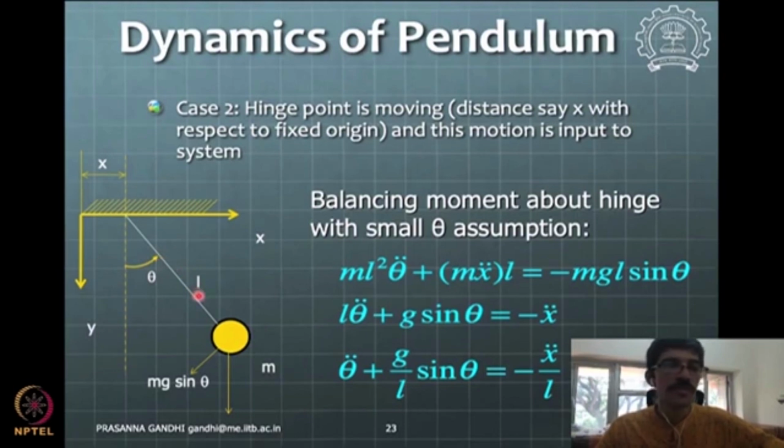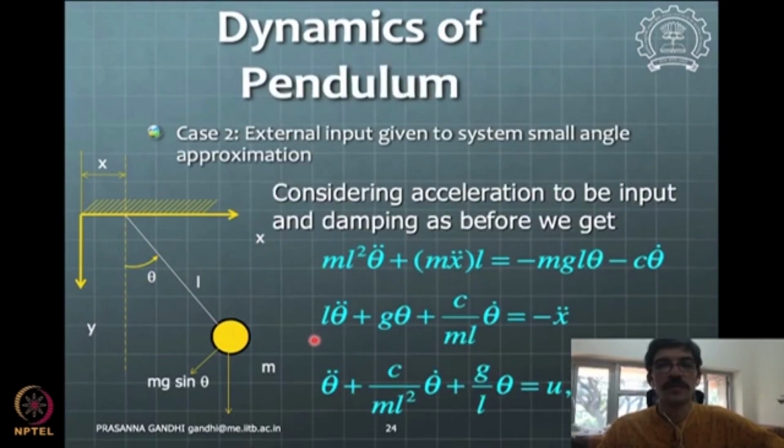Normally giving a torque on the string is not possible, but because I am able to apply this desired acceleration, it is as if I am giving a torque to the string in the direction of theta. And this helps us to develop nice controllers later.